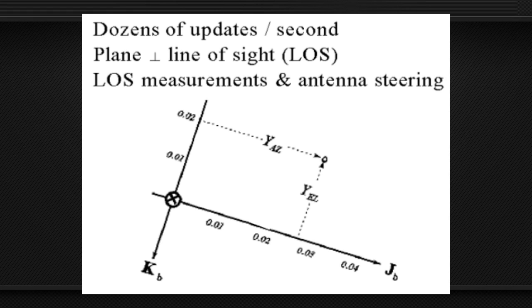To see why those are dominant, first look at the diagram showing a point target in a plane or view like the one just mentioned. In that view, the antenna to target sight line shows up as a discrete dot. With fairly accurate knowledge of radar range, R, we can set the apparent distances along directions JB and KB proportional to products of R multiplied by those small angles.